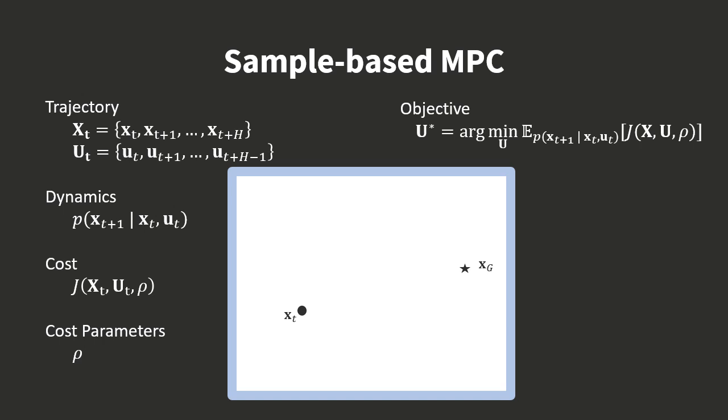Popular sample-based MPC methods iteratively update a nominal control sequence using Gaussian perturbations. This process is only as good as the samples. If we now add obstacles, the samples are high cost. Iteratively resampling leads to us becoming stuck in a local minima.